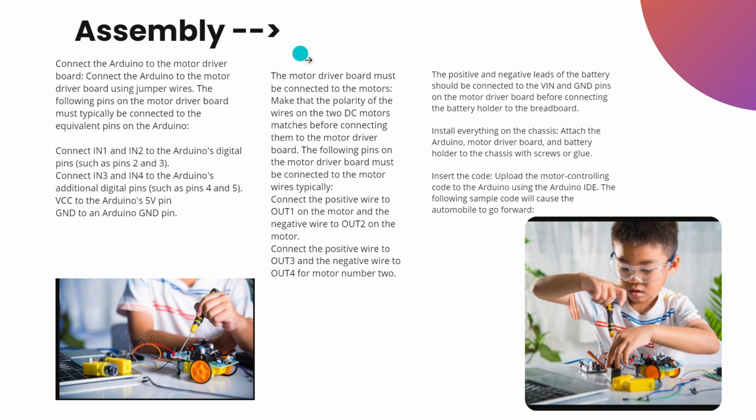The motor driver board must be connected to the motors. Make sure that the polarity of the wires on the 2 DC motors matches before connecting them to the motor driver board. The following pins on the motor driver board must be connected to the motor wires. Typically, these pins I'm talking about. The positive and negative leads of the battery should be connected to the Vin and ground pins on the motor driver board before connecting the battery holder to the breadboard.